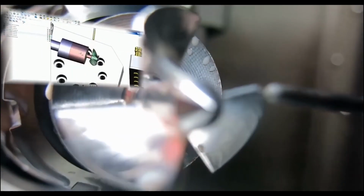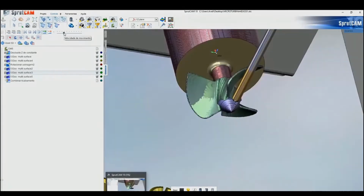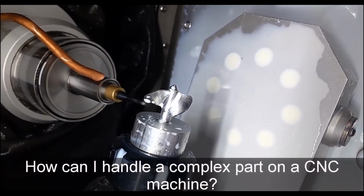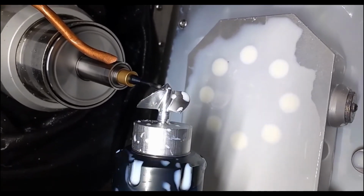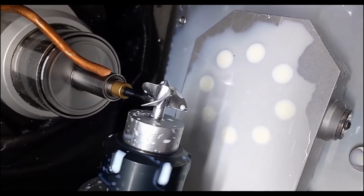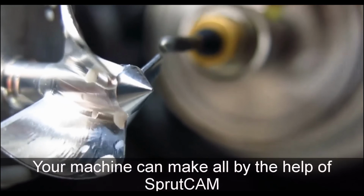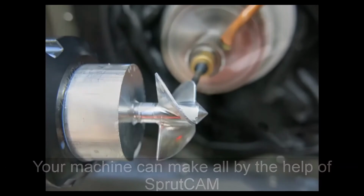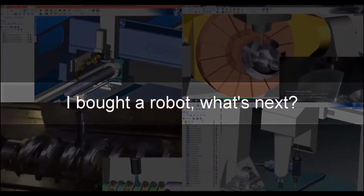The last, the 10th rank, goes to SprutCAM. SprutCAM Robot goes far beyond traditional robot simulation software. It's a single unit for offline programming that includes toolpath calculation for any application, simulation, optimization for singularity and collision-free movement, and post-processing. Toolpaths are calculated in native 6-axis codes, and no transformation is required to go from 5 to 6 axes. A comprehensive robot-specific feature pack is available with collision detection, singularity avoidance, and work zone limit detection.